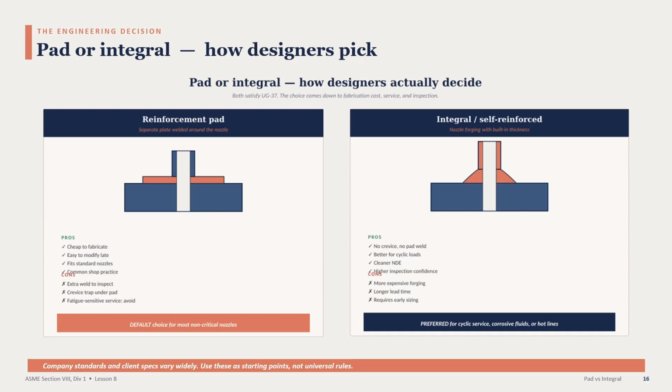Finally, company standards and client specs vary widely. Some clients require pads on everything for consistency. Some clients require integral on all high cycle service. Use these guidelines as starting points, not universal rules. Check what your organization does and what your client specifies.